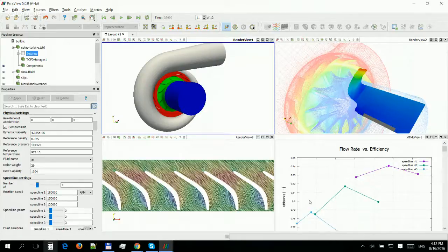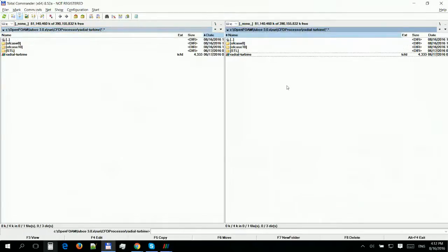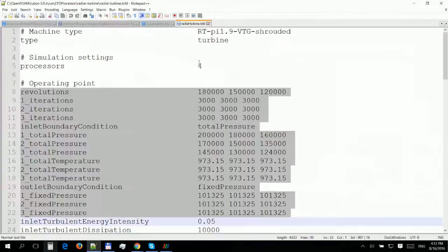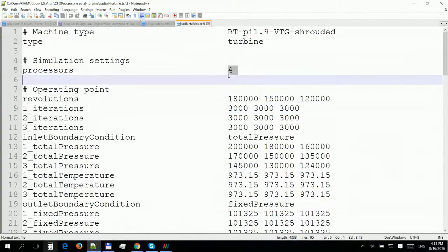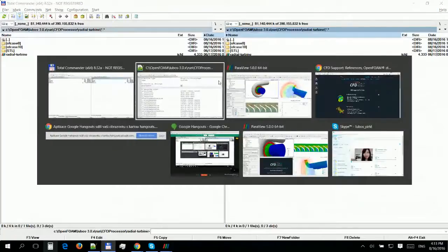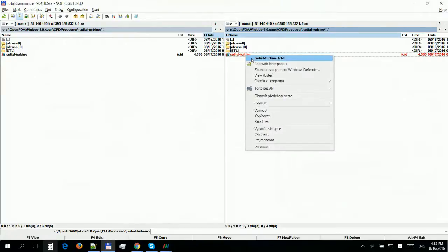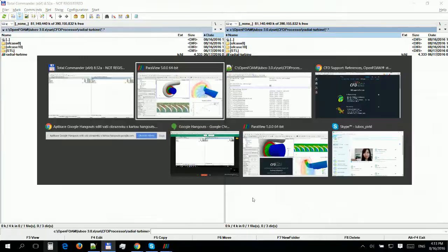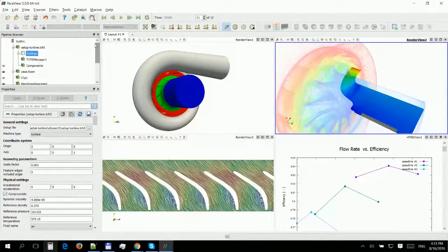Let's take a look at the Radial turbine tutorial. You can download it from the website and load it pretty easily. Each tutorial has its configuration file, which is called radialturbine.tcfd. .tcfd is a special extension for Turbomachinery CFD, and it's a plain text file. I can show you. It's pretty simple, where you can specify all the parameters. But of course, you can also set them in the graphical interface. The very first step in your work would be opening the configuration file in ParaView, which brings you here. Here you can open and close windows and use all those managers, which I'm going to show you now.